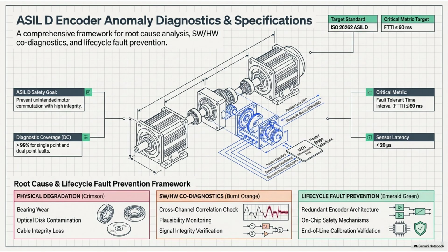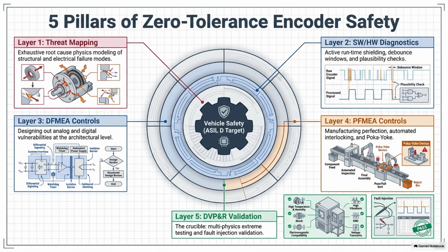But even if the glass survives, the optical system has a secondary vulnerability right at the semiconductor level. Oh, you mean the LED itself? Yeah. When the operating environment consistently exceeds 130 degrees Celsius, the LED suffers from thermal saturation. Because the actual physics of the LEDs start breaking down. Since LEDs rely on the recombination of electrons and holes across a semiconductor band gap to emit photons. Precisely. That's the mechanism. So as the temperature spikes, the kinetic energy of those electrons increases, and they are more likely to recombine non-radiatively, meaning they just generate heat instead of light. Yeah, it becomes a vicious cycle.